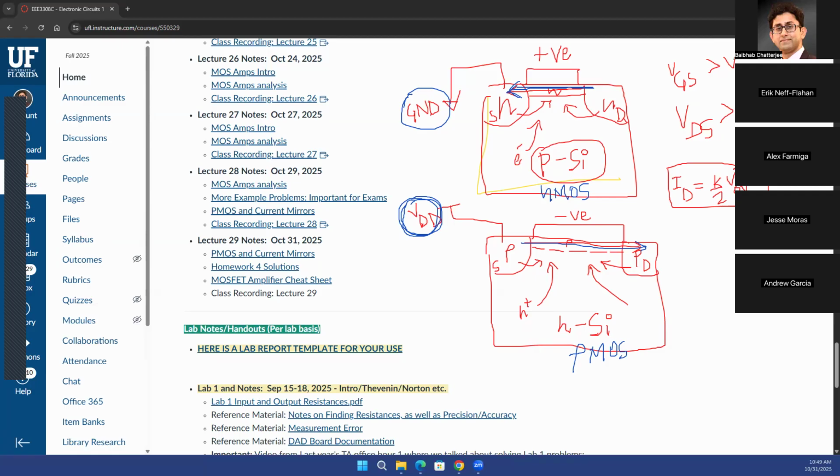But the threshold voltage, remember that we had that concept of threshold voltage, and what threshold voltage really meant is that as you are attracting these minority carriers from the substrate, from the bulk, at some point, your channel will be as much N-type. So let's talk about the NMOS first, and then we'll talk about the PMOS. So for the NMOS, for the top figure, you wanted to create a channel. And when do you say the channel is formed? When your gate to source voltage is equal to your threshold voltage.